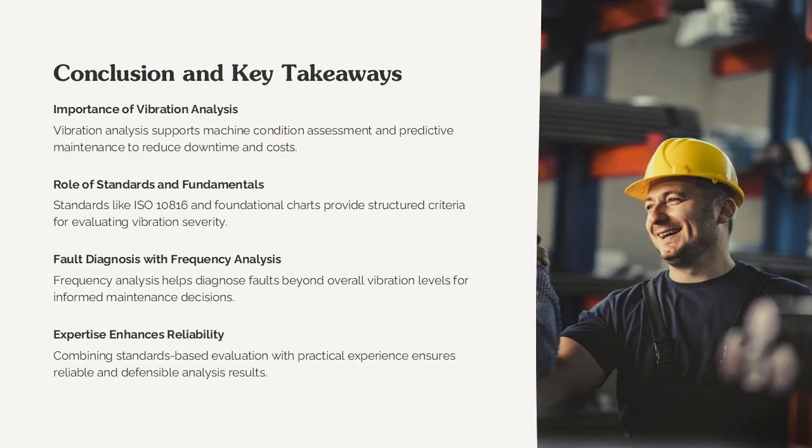Vibration analysis is an essential engineering tool for assessing machine condition and supporting predictive maintenance. Historical references such as the Rathbone chart provide foundational understanding, while modern standards like ISO 10816 deliver structured and globally accepted severity criteria. Understanding vibration fundamentals, measurement units, frequency behavior, and machine context is critical for accurate interpretation. Overall vibration levels indicate severity, but frequency analysis enables fault diagnosis and informed maintenance planning.